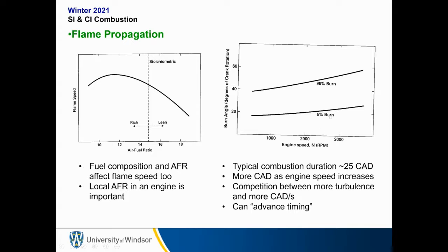We can also advance the timing as engine speed increases, i.e. start the ignition, set the spark off earlier, so more before top dead center crank angle degrees, and that can help alleviate this problem as well.